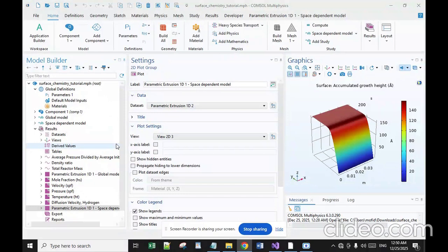The next one is rapid thermal CVD. This CVD process uses heating lamps or other methods to rapidly heat the substrate. Heating only the substrate rather than the gas or chamber walls helps reduce unwanted gas phase reactions that can lead to particle formation.